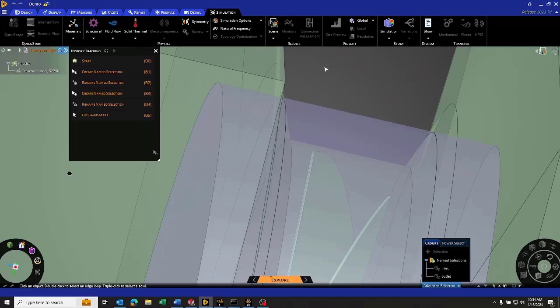This allows us not to lose any of the work, and we can just pass this geometry onto the mesher. We'll reuse all of our mesh controls and setup that were done previously within the mesher, just generating our new mesh, pass that into the solver, reuse all of our boundary conditions, and resolve our model.